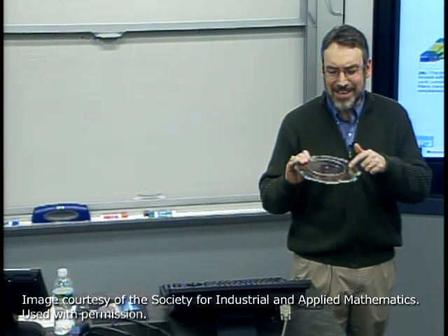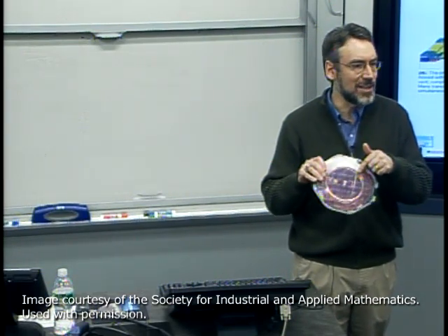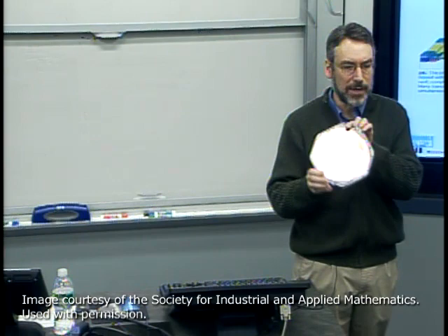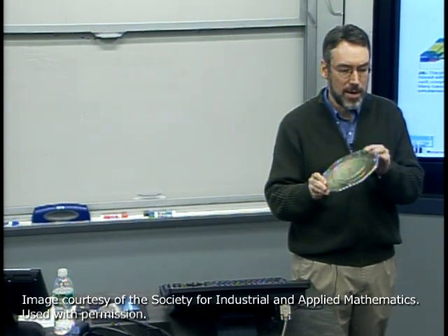In fact, let me hand this around. This just has a copper interconnect test pattern on it. But this is an 8-inch wafer, and the basic idea is we can get that very nicely grown silicon layer and control of the surface of the silicon layer, it's actually quite difficult to build up multiple levels of independent and high quality silicon layers on the wafer.